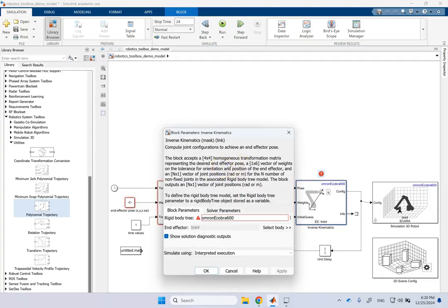Okay, so here you can see it's a 1x6 vector of weights on the tolerances for orientation and position of the end effector. If some position components of the end effector are more important than the orientation components: the first 3 are x, y, z of the end effector, the next are the 3 Euler angles of the end effector. If, for instance, you care more about the end effector being in position than you care about the angle of it, then you can use tighter tolerances for the x, y, z, the first 3 values, and not care too much about the next 3 values.